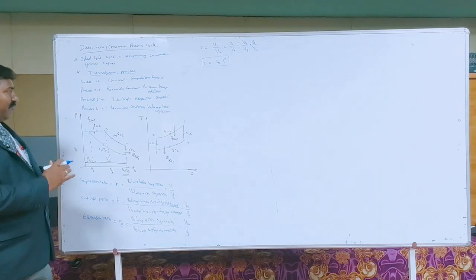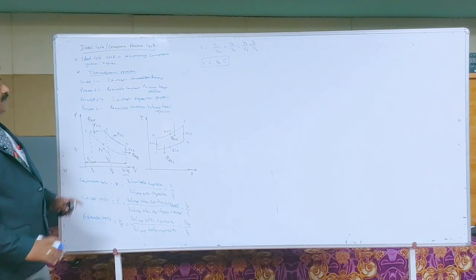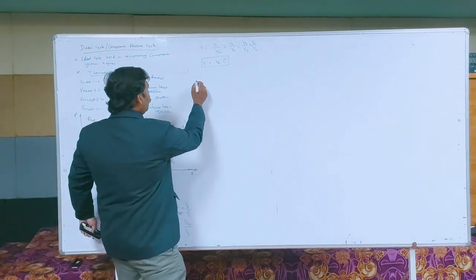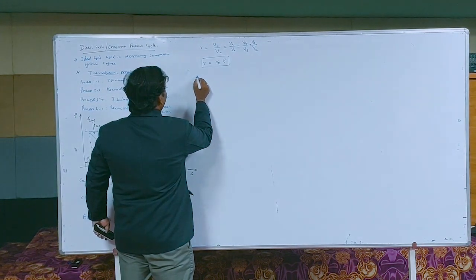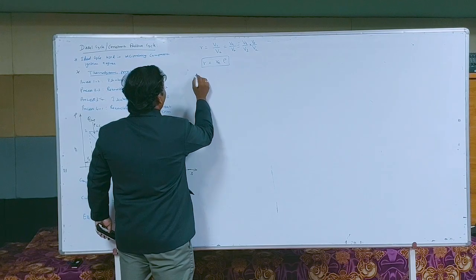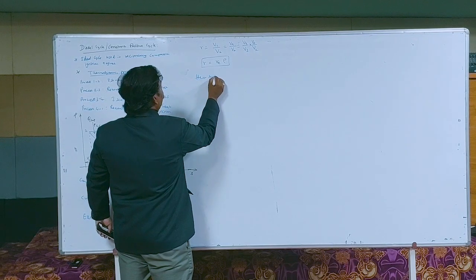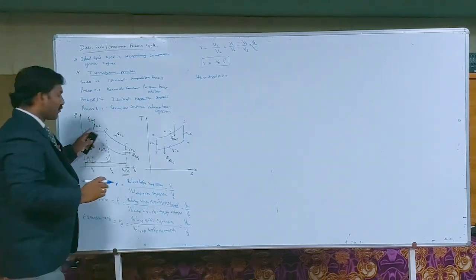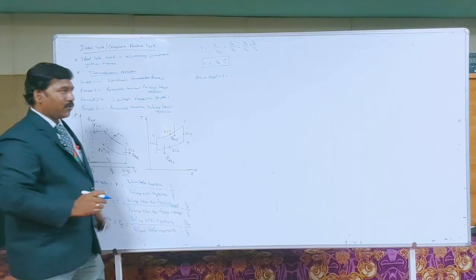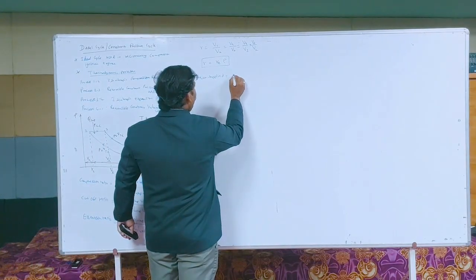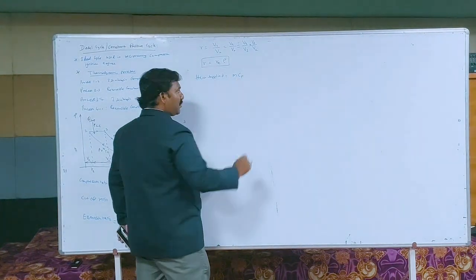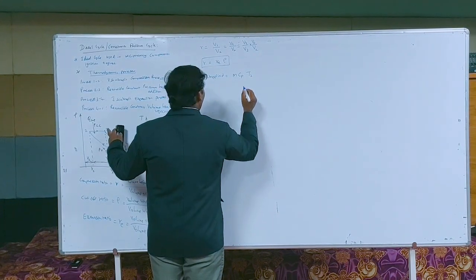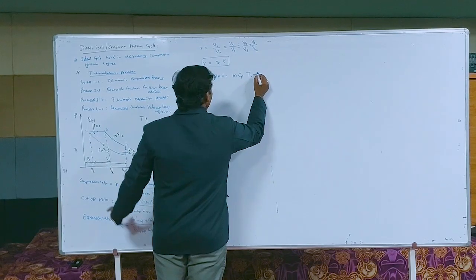So, with this information and input, we will start to derive the efficiency of a diesel cycle. To start with, we have to develop a correlation for the heat supplied. Heat supplied is at constant pressure process. So for a constant pressure process, the heat supplied is equal to m into Cp into T3 minus T2, since after the heat addition the state is 3 and before heat addition the state is 2.